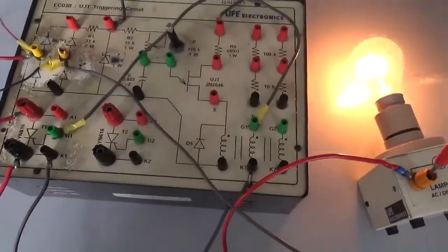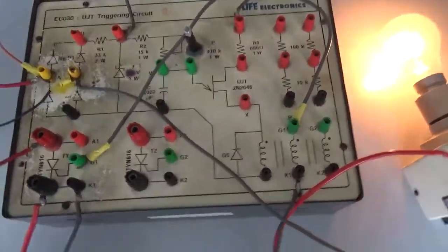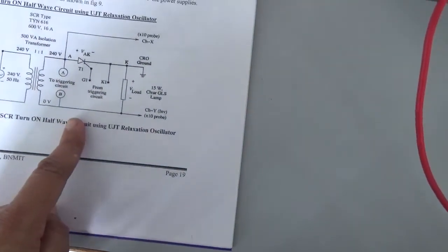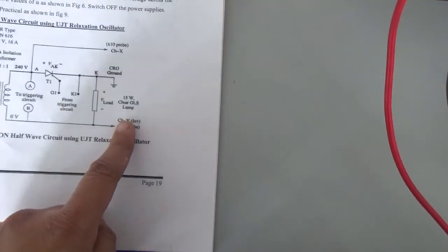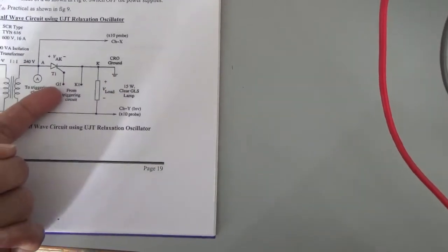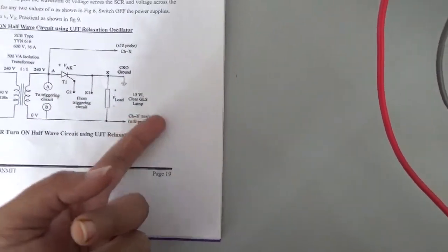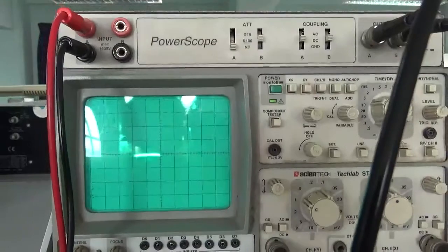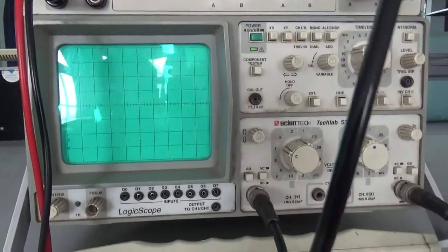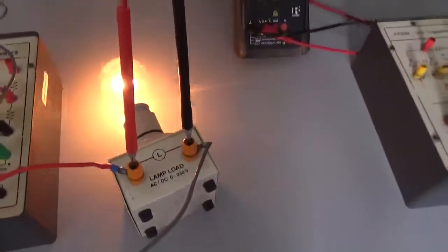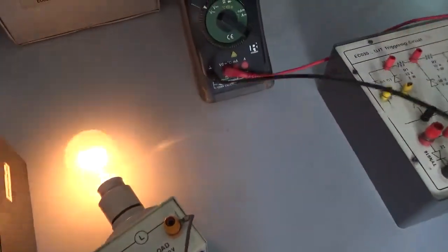It's a controlled rectifier, right? The circuit connection we have done is a half wave controlled rectifier. Now I am interested in understanding what value of voltage I will get at the output for what value of alpha, or as I vary alpha, how the output voltage varies. So I first set alpha by looking at the waveform, to 18, 36, 45 or 90. Then for the same value of alpha, I will measure the voltage across load. You can remove the probe terminals.